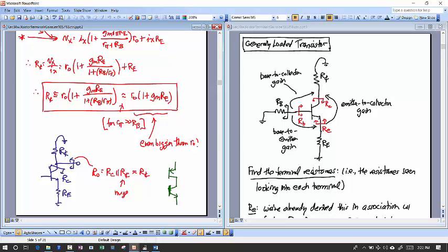I will ask you to memorize that, but if you forget that, it most likely won't matter, because in most circuits, if you have an RC resistor hanging off of this, that RC resistor cannot be gigantic, and so it's probably going to be a lot smaller than this RC, which is now going to be gigantic because it's that original R naught times something that's greater than 1. Okay, so in the end, this whole thing will just boil down to that RC. And last time I forgot to put the line down that final C. It's there now. That's the C that I meant for that.